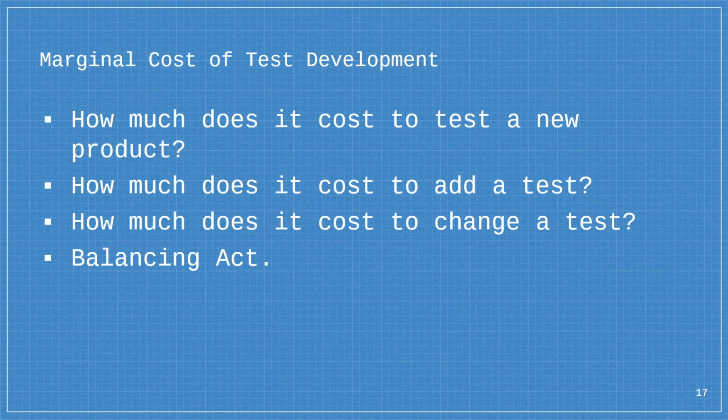So the advantage of this is that you will typically end up with, for a specific set of products, a set of standard interfaces that make life a lot easier once you understand what that is. So one of the things that I would recommend is if you're going to do a custom interface panel for your system, then use a DB series connector, so a DB25 or DB62 or something on there.